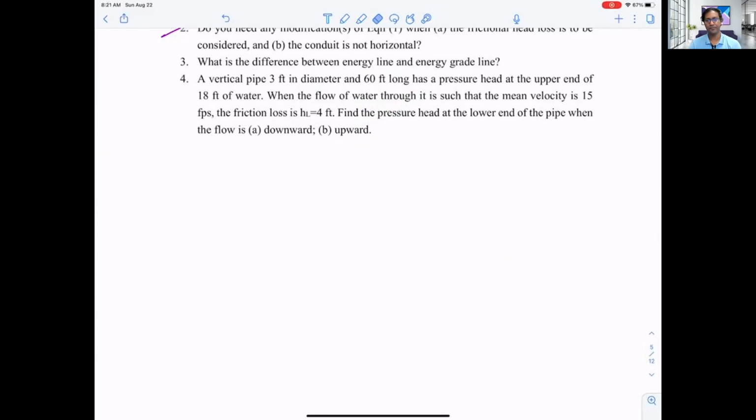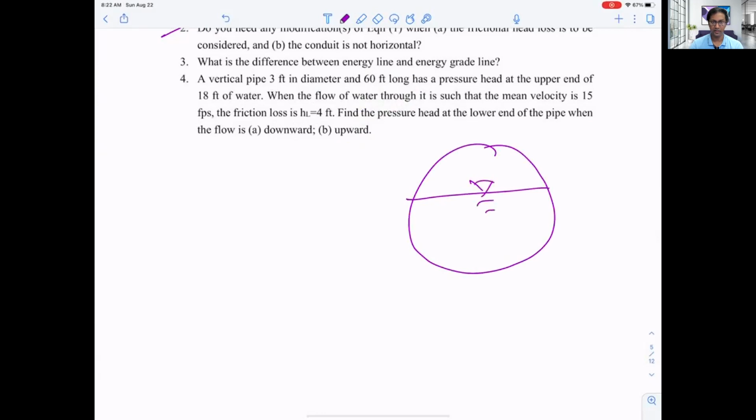However, if the flow is happening through a pipe of a certain diameter, and there is no atmospheric pressure inside that pipe, rather than the pressure we have, it is a gauge pressure, we call it a pipe flow. And pipe flow may also be open channel flow. Water flows through a pipe, and if the pipe is not full, like water is not flowing full, then this will also be open channel flow, even though it is flowing through a pipe.